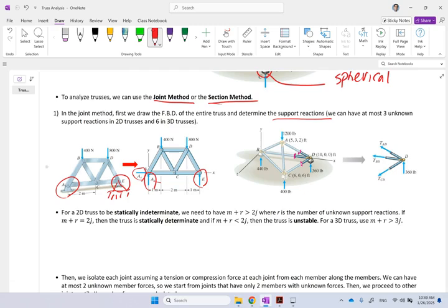Okay, so in a truss, you ideally do not want more than three reactions, and you want to have this portion a little easy to move left and right if possible, so it does not add extra stress in the members due to thermal expansion or contraction. That's a separate story, whether you have to leave it as a roller or pin it down or something. So